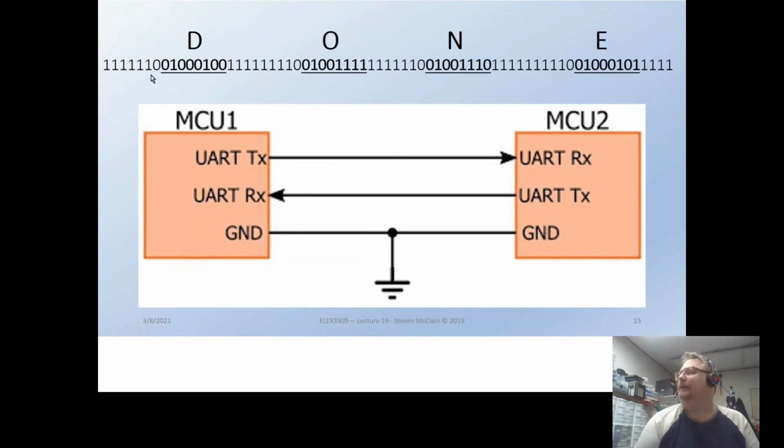Yeah. So it's just a one until it turns into a zero, and once it's a zero, that's our start bit. There's our data, and there's our stop bit, which is going to be a one always. And then we've got nothing left to send, so it just stays at a one until we get another start bit. And there's our data for that one, with a one as our stop bit, and so on and so on. Cool. Instead of it being 1, 1, 1, 1, 1, 1, it's really just one.